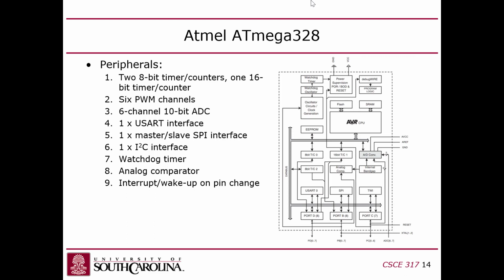There's a watchdog timer, an analog comparator, and an interrupt or wake up on pin change, which is kind of cool. This allows you to put the chip into a low power state, and then whenever one of the input pins changes, it'll automatically wake up.